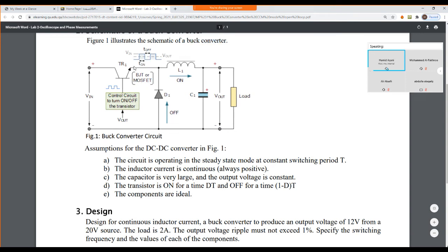The buck converter, as I told you last time, starts with the switch here. We can cut the input according to the frequency of open and close, on and off, for this switch, to make Vin at this point similar to a square wave like that. By doing this, the Vout is the average of that square wave. So if you keep the switch closed for more time, a duty cycle of more than 50%, you are going to increase Vout. It's the average.